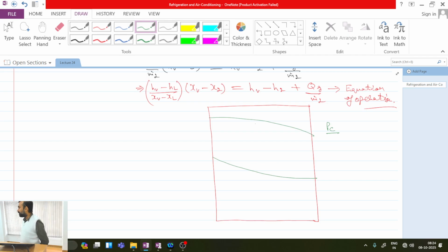Liquid and vapor should not lie on the same isotherm. In order for the transfer of heat, vapor should have slightly higher temperature than the liquid temperature. So say somewhere over here is my vapor and here I am having liquid, where the isotherm passing through this is this. So this is the isotherm. It means vapor is on the left of the isotherm, which means the temperature of the vapor is more. Are all clear with this point or not? Now what will happen? Tell me.